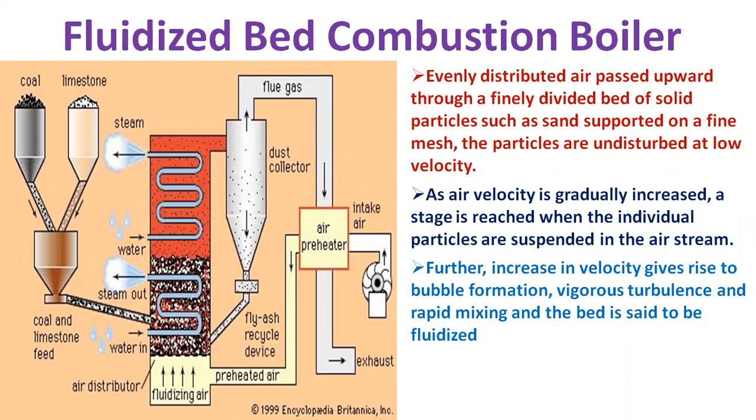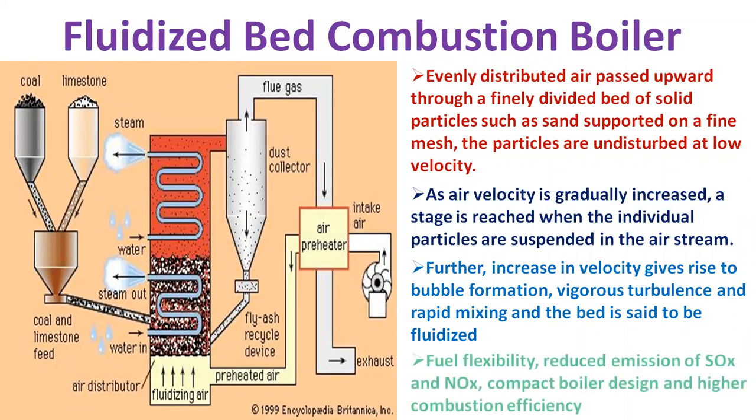be fluidized. If the sand in a fluidized state is heated to the ignition temperature of the coal, and coal is injected continuously into the bed, the coal will burn rapidly and the bed attains a uniform temperature due to effective mixing. Proper air distribution is vital for maintaining uniform fluidization across the bed. Ash is disposed of as dry and wet ash as system demands.